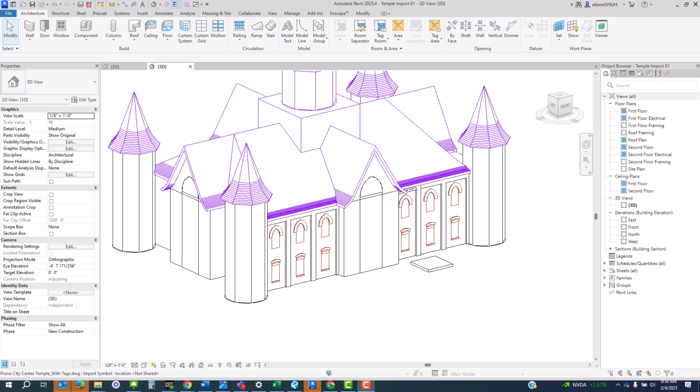In this video, I'm going to teach you how to create a new family, how to understand that family environment, and how to use work planes to create the geometry that you need. To begin, let's go ahead and open up a new project.